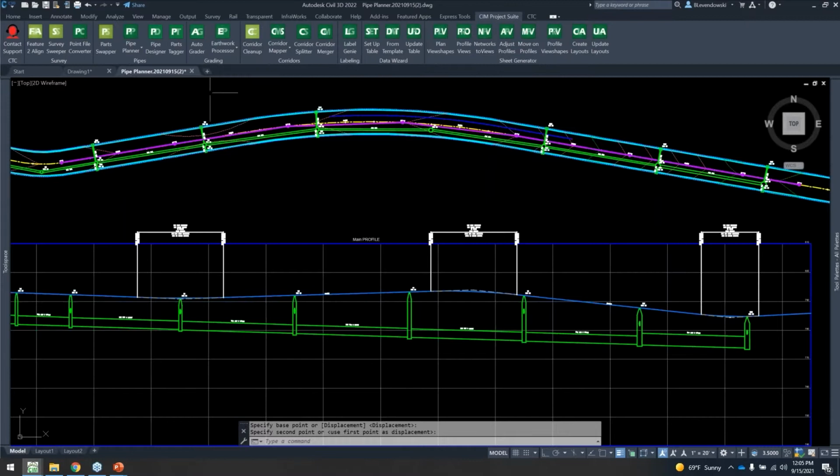In the Project Suite, that's what Pipe Planner is part of. A new tool, like I said, that we added just a couple months ago. It came out in the 22 release, and we've made some tweaks and improvements in some point releases since then. We're at the 22.0.2 release right now, so if you're not on that, be sure to update. We've got two sub-commands here: edit, export pipe networks, and import spreadsheet. That was the option where you take edits from Excel and import them back in to update your pipe networks. Our focus will be on using the primary function, the edit, export pipe networks tool.